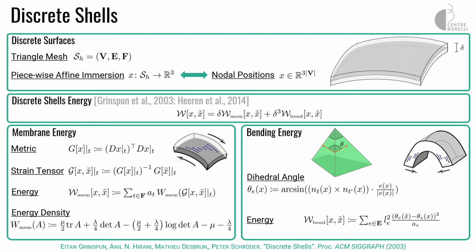Yes, you integrate on the X, but you are doing a change of variable. You have a Jacobian, or you have to compute the area of a triangle after the deformation. No, before the deformation. Okay, yes, there is a change of variable in here. You could also write this as an integral over the deformed configuration, but we typically write it as an integral over the undeformed configuration. Because also, maybe I have to go a step back.